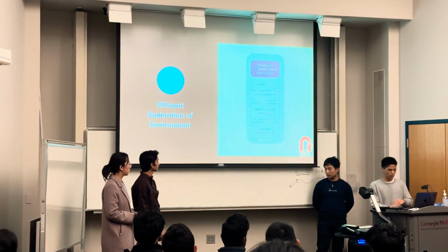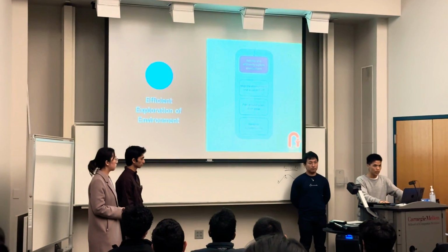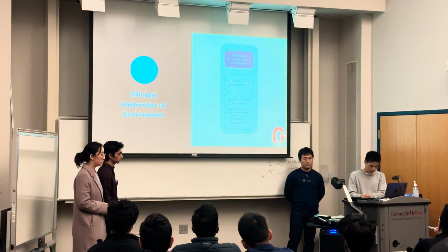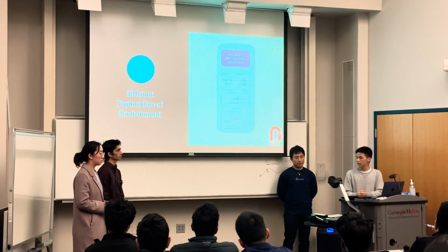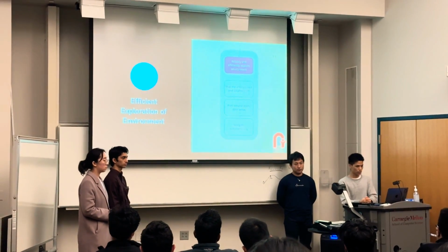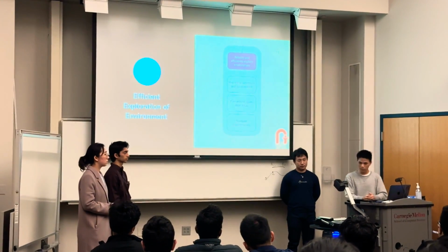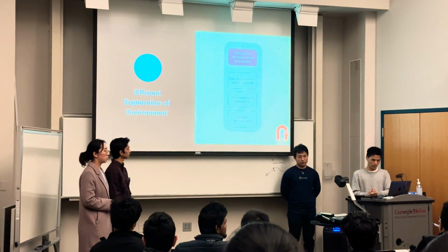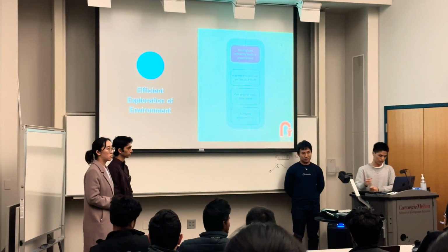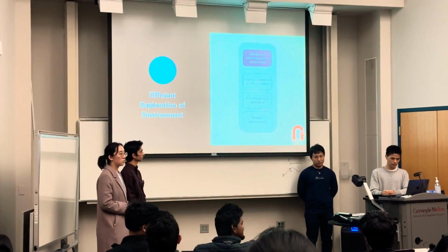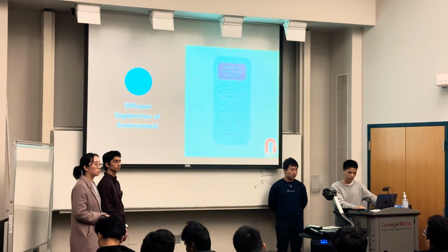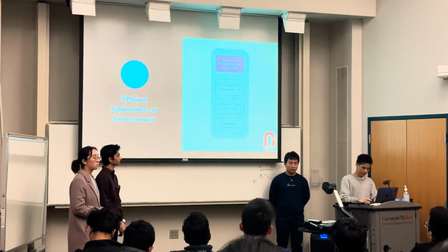The first thing we want to do is to make sure the robot covers enough area before the stranded person is dead. So the robot has to map and localize itself, since there is no prior map. It should also be able to plan its path to places where the doors are open. By setting that limitation, we don't have to deal with robot manipulation for the doorknobs. And the last part is that the autonomous navigation feature avoids communication issues with the firefighters and enables faster response time.